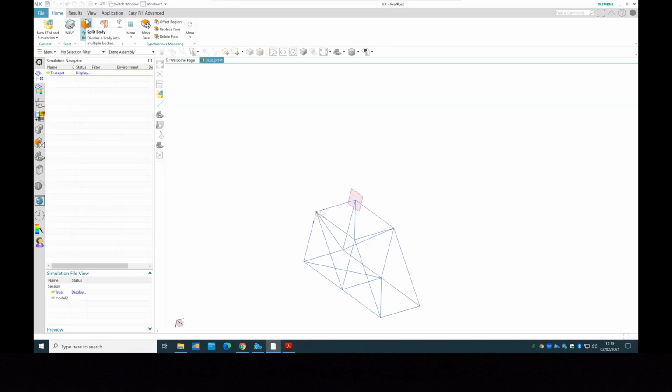And a split body, rather than studying the full body, if for instance it's completely symmetrical, you want to save some time, especially in processing, because if you have a complex geometry, FEA might take a long time, depending on how powerful your computer is. In industry, if you have a complex geometry, they use cluster computers. They have to connect hundreds and thousands of computers to be able to process it, and it is quite common in industry, to be honest, because these machines won't be able to do a really complex structure like a bridge. So then you try to simplify it by using the split body.